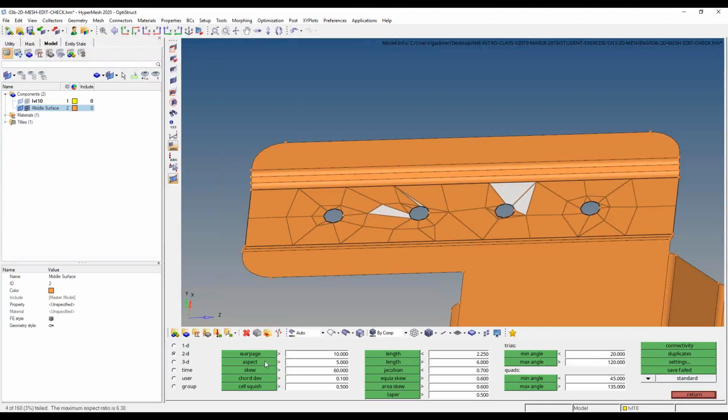I don't want to scare people into thinking that just because you don't have perfect aspect ratios, your mesh is poor. That might just be that way because that's how the part is designed. It's inherent to the shape of the part that you can't always map any given arbitrary area with perfectly shaped squares and triangles. There's going to have to be a little bit of wiggle room to make that area possible.